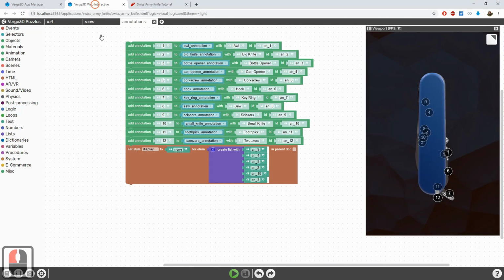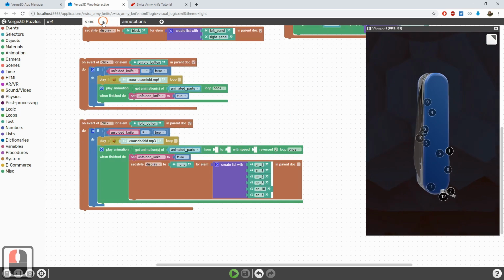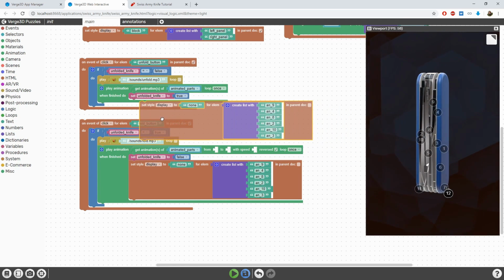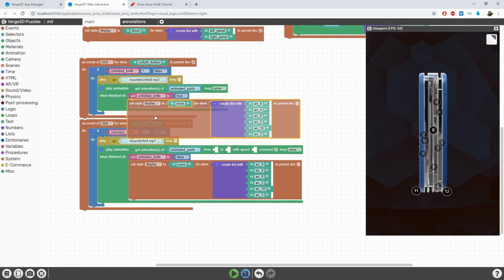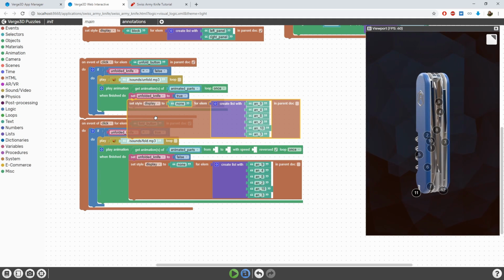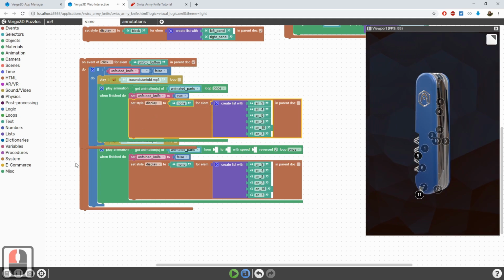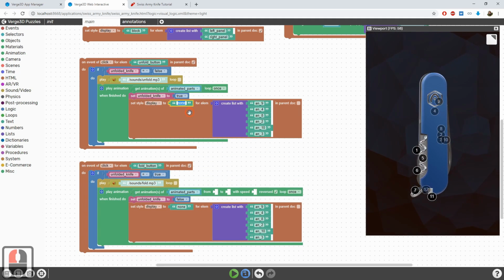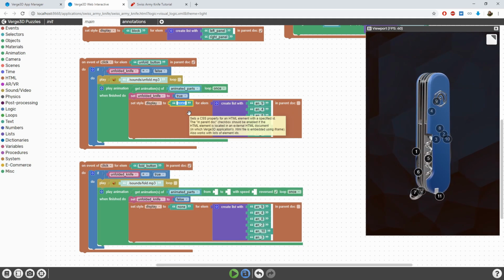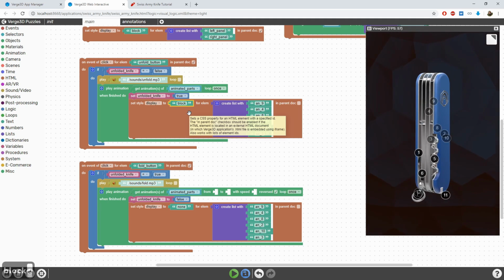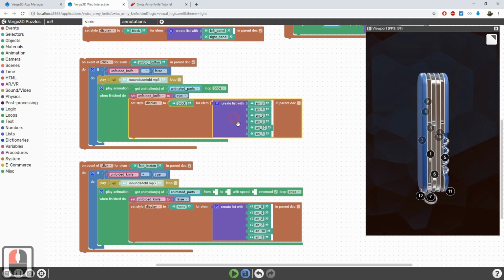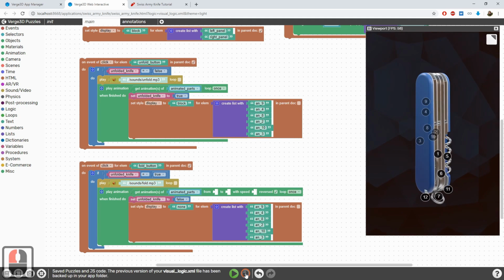However, the hidden annotations should be revealed once the knife unfolds. To do this, simply copy these puzzles again and paste them inside the unfolding animation puzzle. Setting display to block reveals HTML elements. As a result, once the unfolding animation is finished, previously hidden annotations show up.